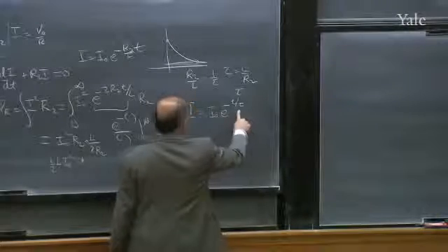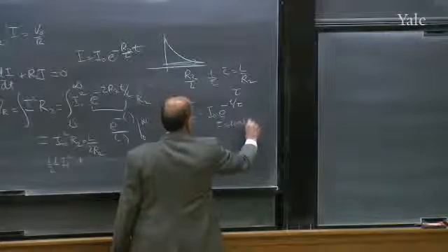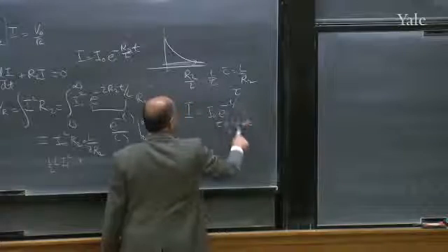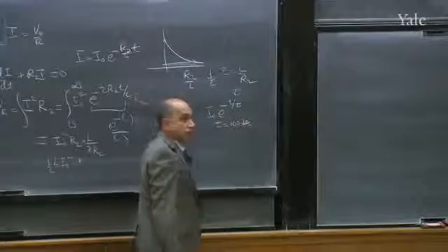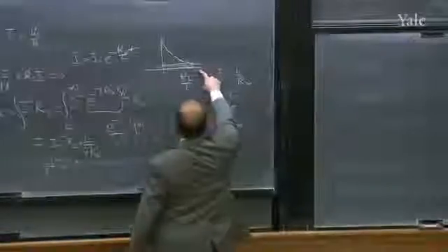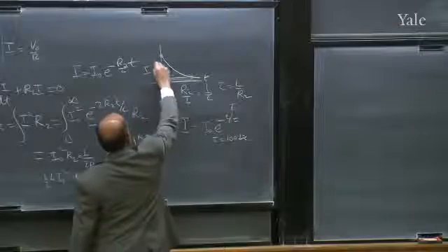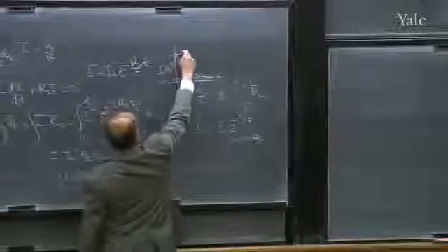We always like to write it in this form so that if tau is equal to 100 seconds, you will have to wait many multiples of 100 seconds before the current is negligible. What are the units on the axis? Oh, in this graph here, this is time, and this is the current in the loop. It starts out at some initial value.